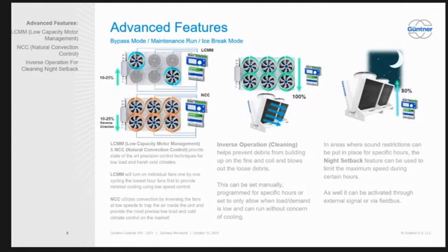Yeah, so you can do that. You can also do a custom signal if you want. If you want to do 2 to 10 or 5 to 10 or 4 to 20 milliamps or 0 to 20 milliamps, it's our newest controller. Like I said, because it's a full blown Linux computer, it's very versatile. So that's something that's nice.